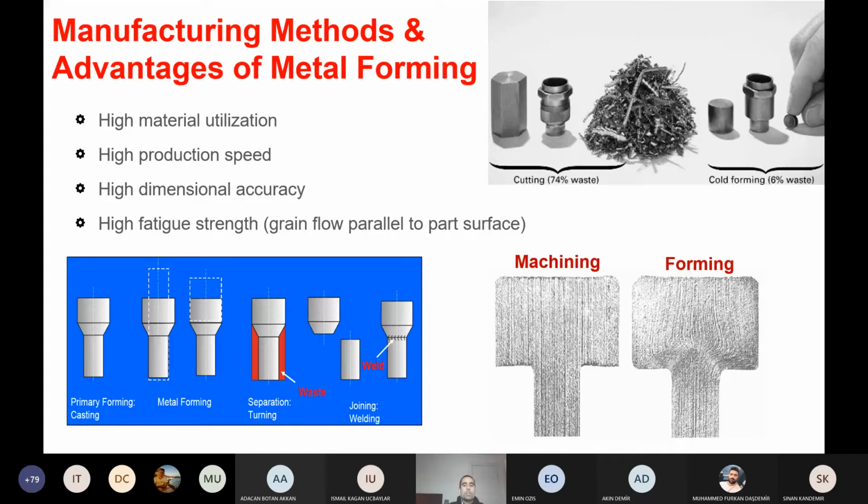So I'm of course generalizing this statement. There might be some exceptional cases where a special casting technique is used, or a special surface finish technique is used on a machined part, which can improve the life of those parts. But in the raw condition, when we have this head-to-head comparison, in the majority of cases, forged parts will show a better fatigue life.